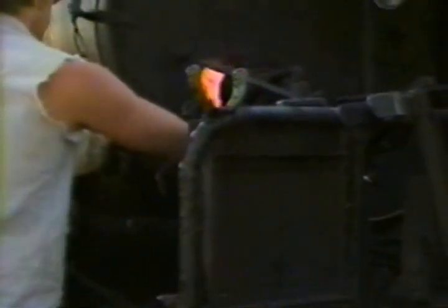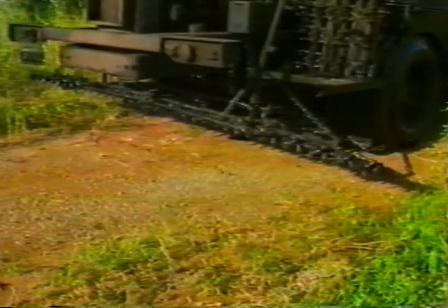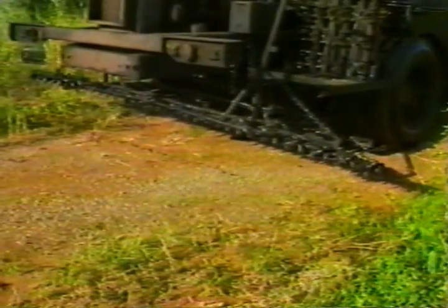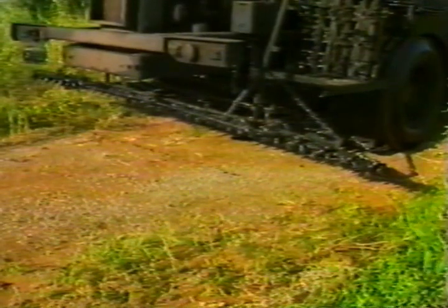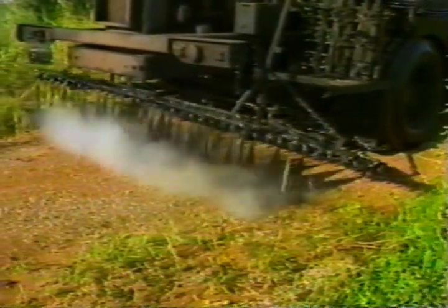A full distributor tank does not eliminate all danger when firing the burners. Faulty plumbing is likely to give the operator a surprise. Telltale vapors, drips, and frost buildups all indicate leaks in the propane burner systems. A poorly maintained spray bar with a heavy buildup of cured binder usually leads to partially clogged nozzles and, consequently, an irregular fan pattern. Improper nozzle settings may compound the problem and result in a seriously uneven binder application.